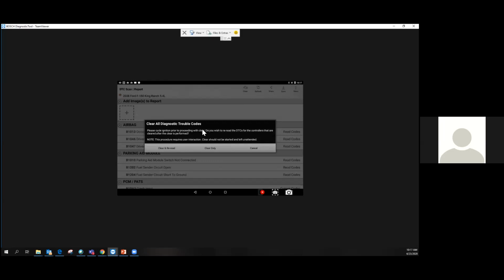It's going to clear the modules out. It's going to go back and rerun the scan on that vehicle. And that ensures that the fault code actually cleared out. That way, if you do have a hard fault, something that wasn't repaired, something that was left disconnected, maybe